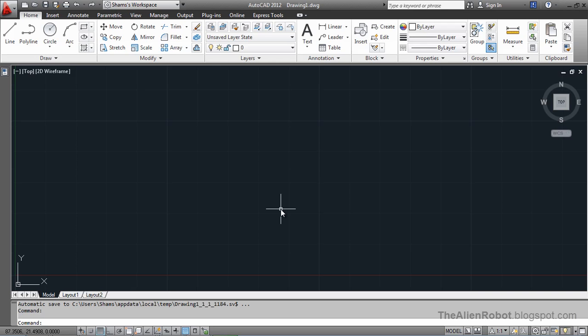As you see, I'm back in AutoCAD. I'm sitting in the default Drawing1, and we're going to see those features here in AutoCAD. You see here this little cube that has the x and y on both sides of it, and this is called the UCS, and it's here to help us find the coordinates. The red line represents the x direction, and the green line represents the positive part of the y direction on our grid.